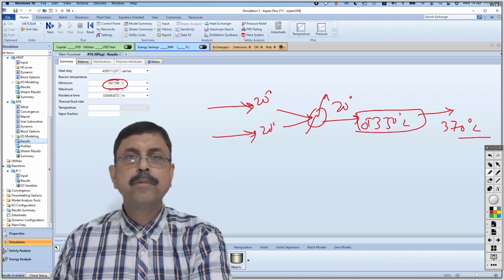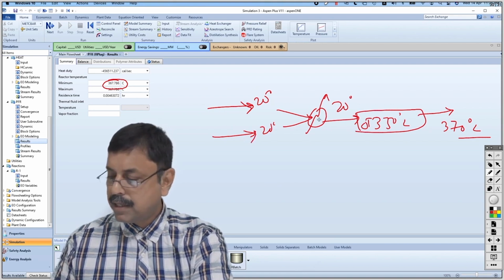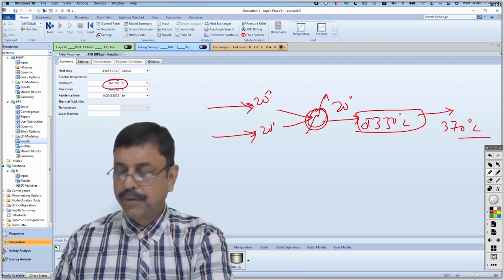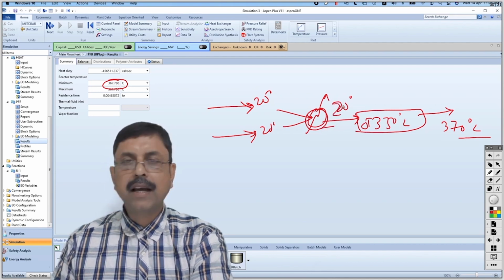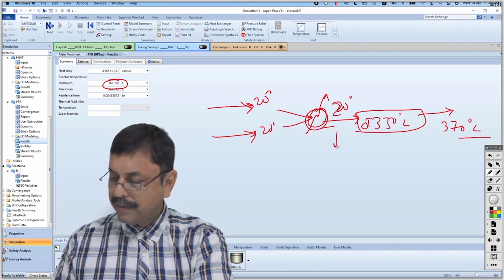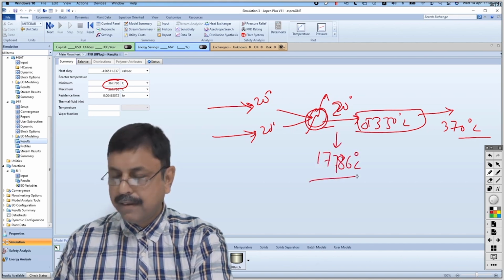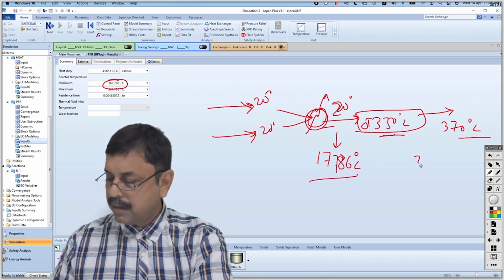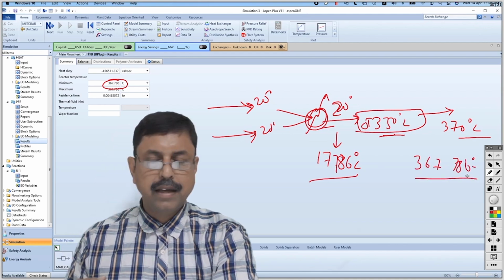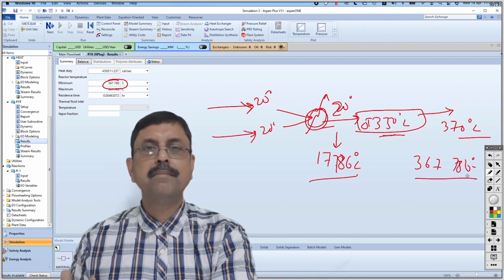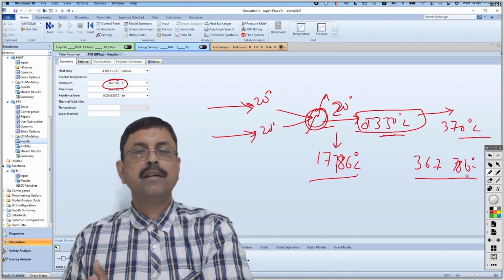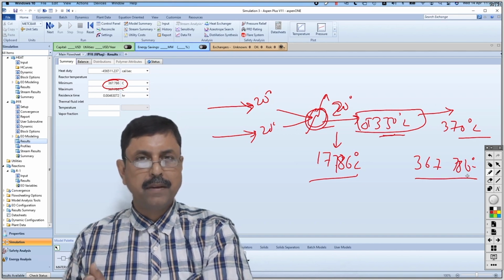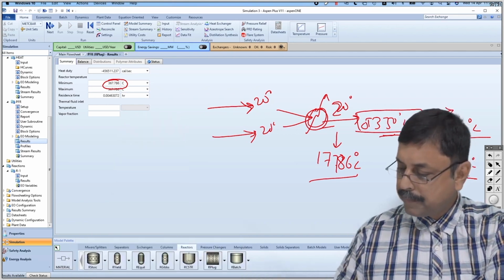Benzene and propene, butane, this combination, they are getting mixed over here. So the combined mixture is no longer at 20 degrees centigrade. It is coming below that. And as a result, with the temperature rise of 350, we are getting 367.786 degrees centigrade. This is the advantage of leaving certain calculations with Aspen. It will provide more realistic picture if it is allowed so. Okay.